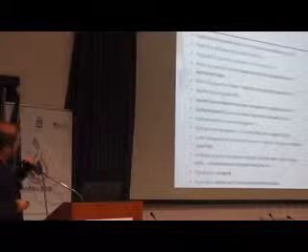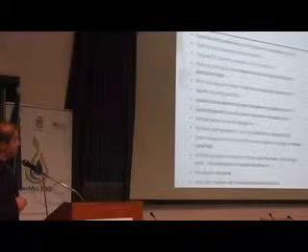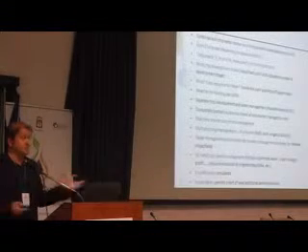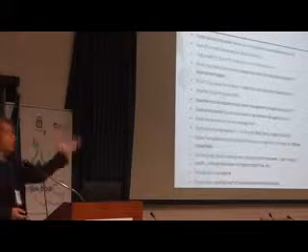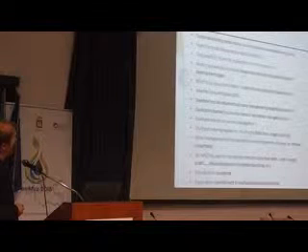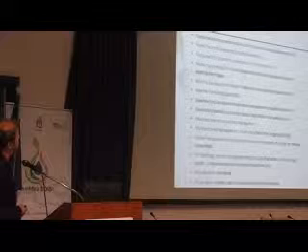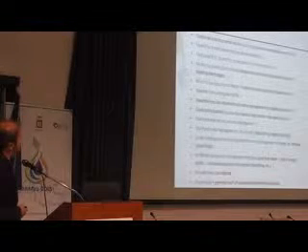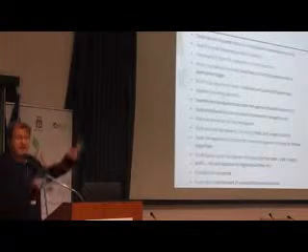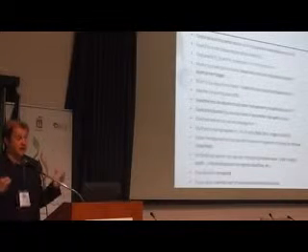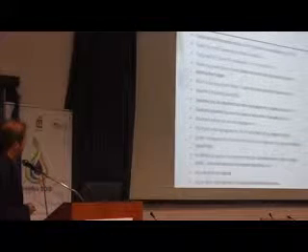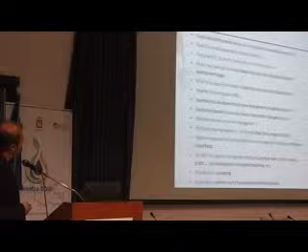We are going to use different approaches for estimation of reference evapotranspiration, because depending on the available data inside the software, we can decide if we are going to use the Penman-Monteith equation, or only the temperature data, or whatever other method. We are going to apply adjustable coefficients for solar radiation, and we are going to check also Kc values for local conditions, because we have Kc from the literature, but we have Kc values that reflect the real conditions of the field. We are going to use a multi-crop development model.